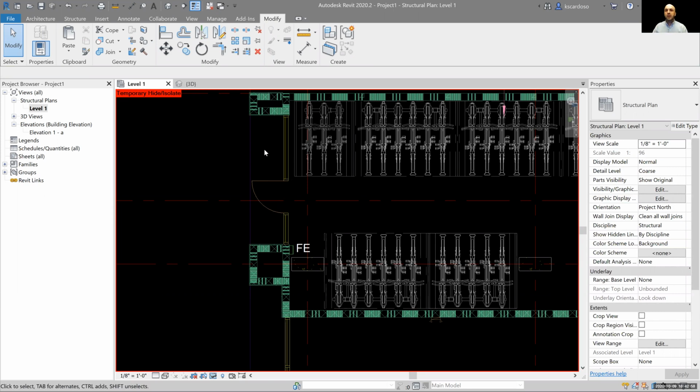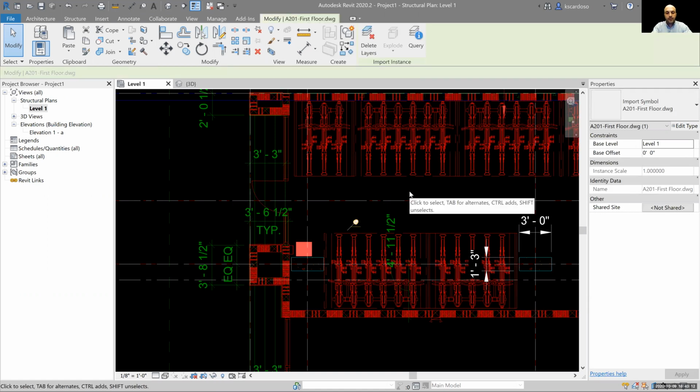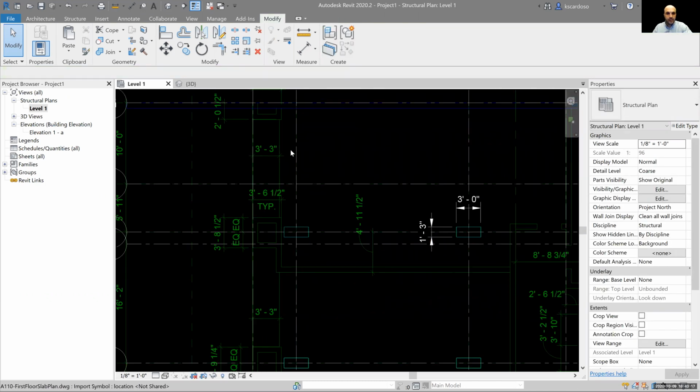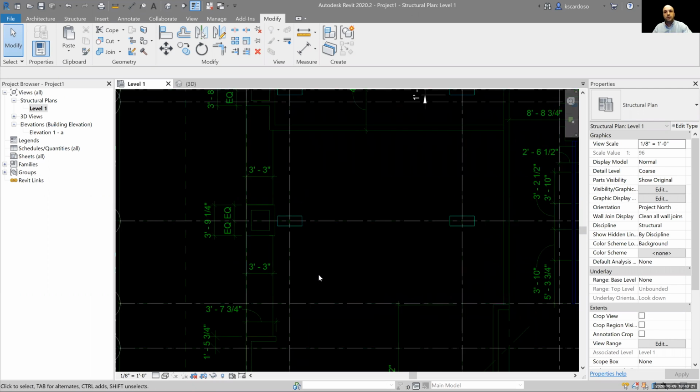We've spoken with the architect. We know what his design intent is, and he really means that they want to step down there, all right? So let's restore our view, HR. We can now turn off this architectural floor plan. So select it and type in HC for hide category. And now everywhere we see a 3'3" situation, we already know we're going to step down.